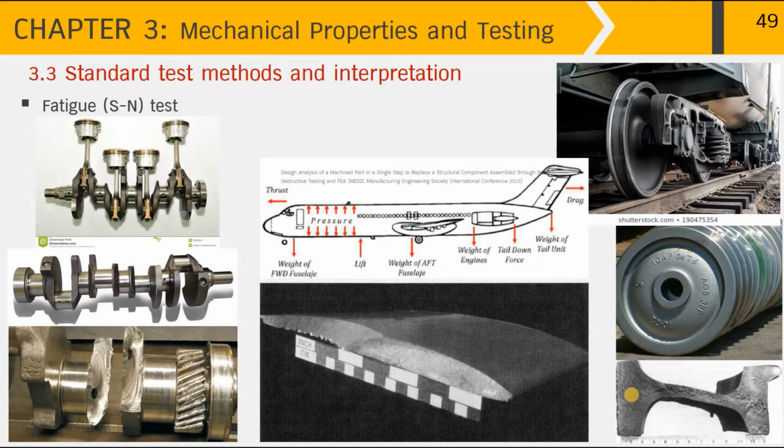From these three examples, you will see something in common, which is that the fracture surfaces are flat with no gross plastic deformation. Also, we can see the beach mark with our naked eyes. The flat surface shows less deformation and a brittle type of fracture. So fatigue failure is considered to be quite dangerous and needs to be studied in more detail.